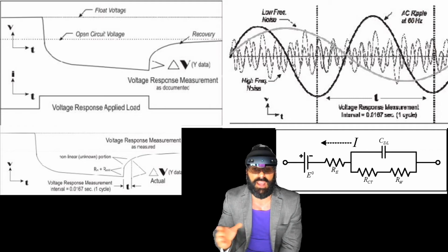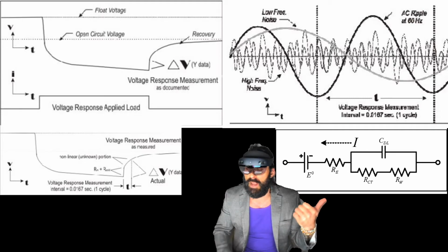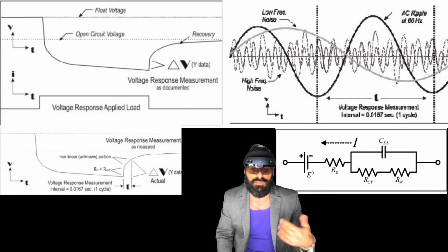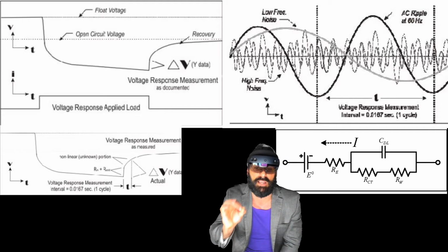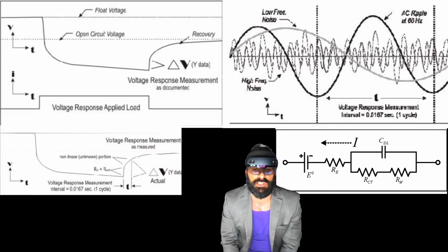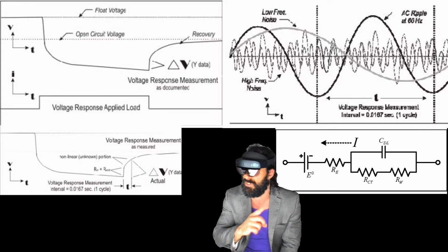Now, generally, if you look at that same Randles circuit, because of the capacitive reactance, a single-frequency testing methodology will see all of the components as one complex impedance. They call that the modulus of Z. The majority of that contribution is coming from the conductance of the first resistor, right?